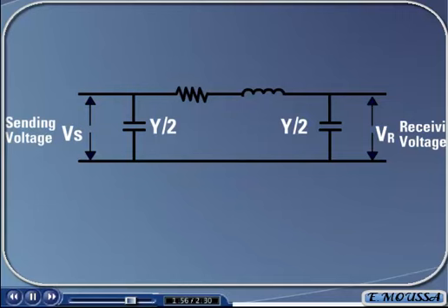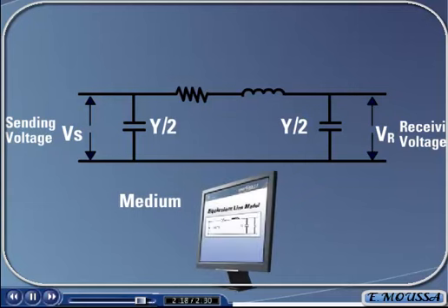Different models of transmission lines are used for different lengths of line. These models are in three categories: short, medium, and long lines. The pi model shown here was historically used by the protection engineer to represent medium-length lines. However, by using this representation of the line, in addition to computer-aided software now readily available, the protection engineer can accurately calculate all required values for both medium and long transmission lines. This data simplifies the protection engineer's task in performing fault calculations to set up the distance protection within a relay.